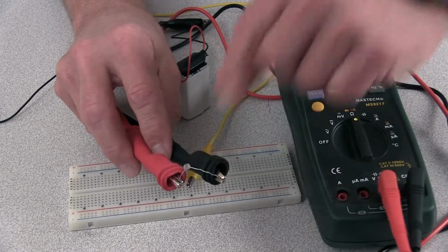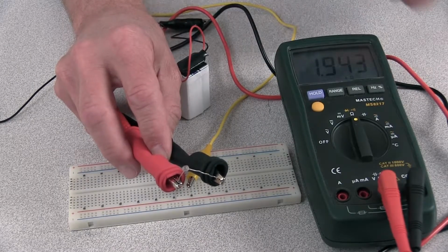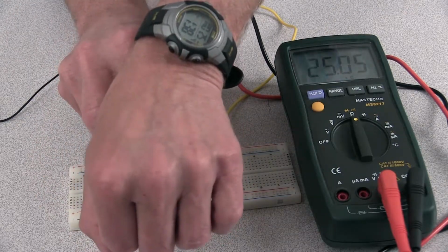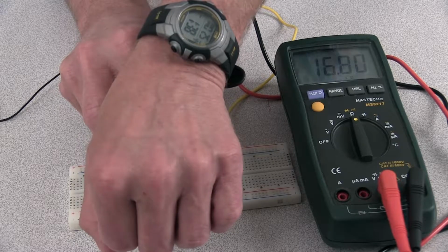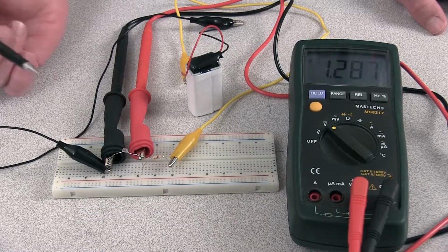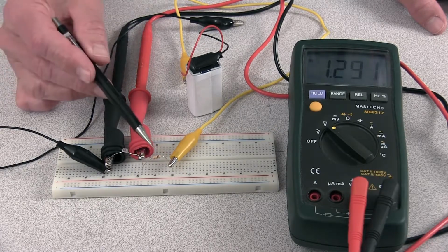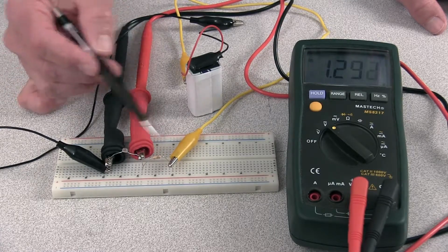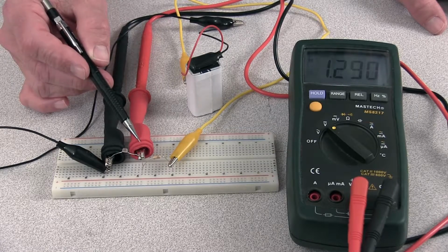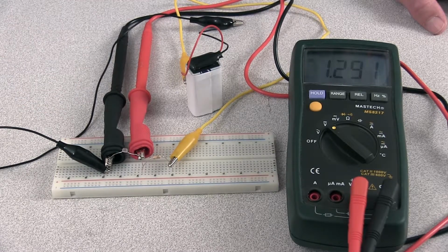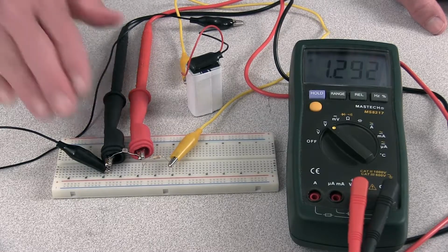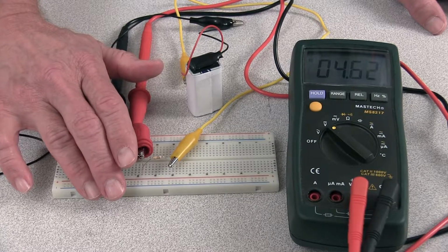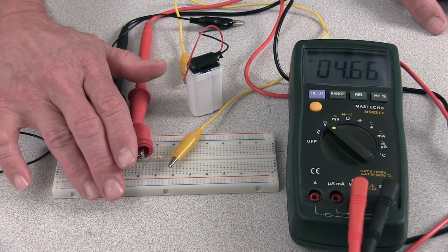This is a photoresistor. I'm using this DMM to measure its resistance. Under light conditions, it's got about a 2 kilo ohm resistance, but if I cover it over, the resistance goes up to about 17 kilo ohms. I can convert this resistance change to a voltage change by connecting this photoresistor to this resistor here and applying a 9-volt difference using this battery across the two. If I measure the voltage across the photoresistor using this DMM now, under light conditions I have about 1.3 volts. If I cover it up, that voltage changes to about 4.5 volts. So I've converted the light level change to a voltage change.